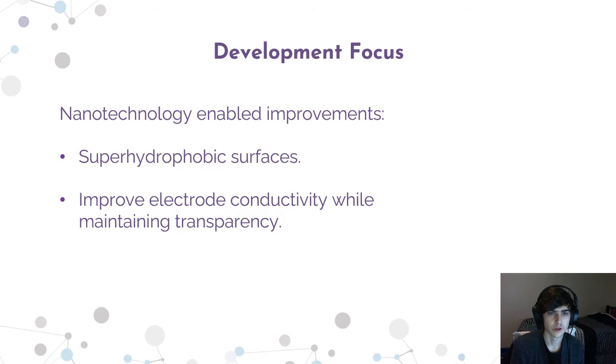Our nanotechnology background will allow us to improve upon previous demonstrations of TENG technology in two main areas. First, we hope to fabricate nanostructures in our dielectric layer to improve the hydrophobicity of the TENG device's surface. As previously mentioned, we also aim to utilize transparent electrodes to expand the range of applications for a device. Indium-doped tin oxide is a frequently used transparent electrode material, but presents drawbacks due to its higher sheet resistance compared to metal electrodes, limiting device efficiency. We therefore aim to fabricate electrodes that improve device conductivity while maintaining transparency.